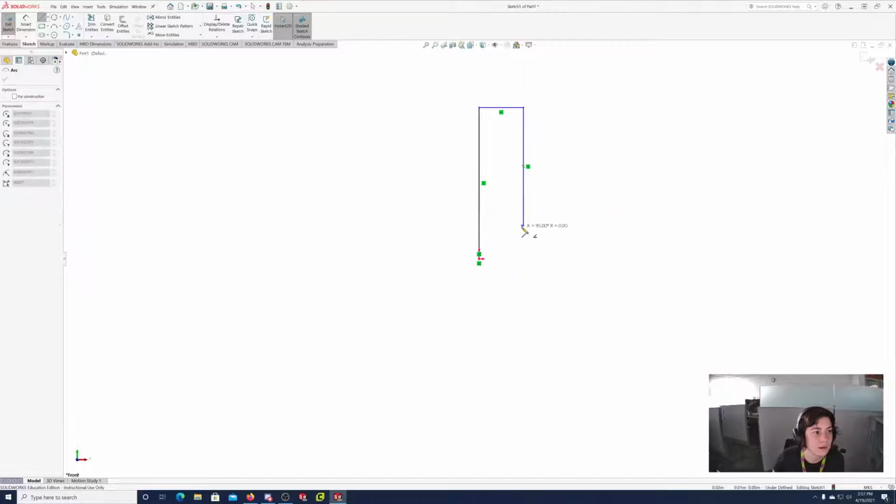But one thing that it mentions is you can hover the cursor back over where you stopped your line, and you can do an arc instead of a line without actually going up to select the arc tool. So I can make an arc in whatever direction I want. To make it back into a line, you just hover over that point again. Well, it's still an arc. Okay. And then if you go straight out, I guess you can still do an arc.